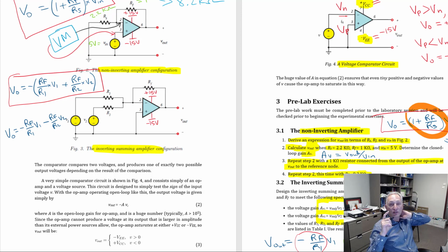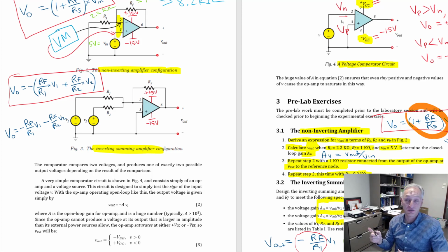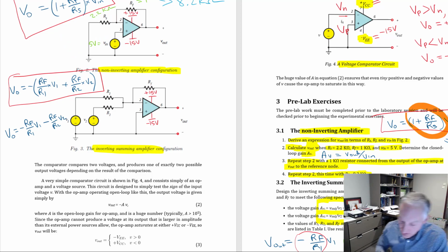And so remember the summing point constraints for the op amp. If we have negative feedback, then there's a virtual short circuit between the two input nodes. So my voltmeter should ideally measure 0 volts. Okay, it should appear like a short circuit, even though there's no wire that looks like it's connecting these two together, right? So these two, it looks like they're connected. That's what virtual short circuit means. And so the voltage between them should be 0. There's no wire connecting them. It's just the op-amp behavior that forces this kind of phenomenon. Okay, so that's that measurement.